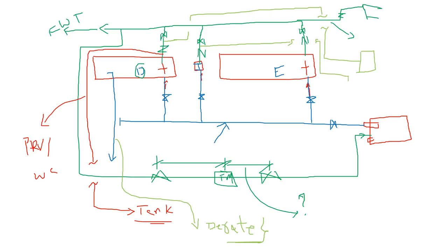From the electric pump also we will consider a pressure sensing line, and you will have a check valve and drain valve and all those things. You need to refer to NFPA 20 about the valve types which need to be installed in the pressure sensing line. So this will be the electric controller. Basically, this pressure sensing line will sense the variation in pressures, which will help to start the fire pumps. So here, for example, this will be the diesel controller, jockey controller and electric controller.